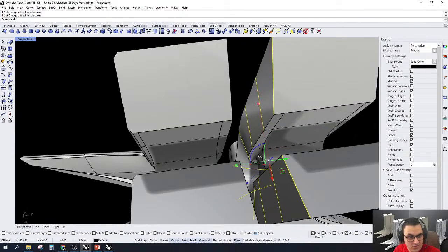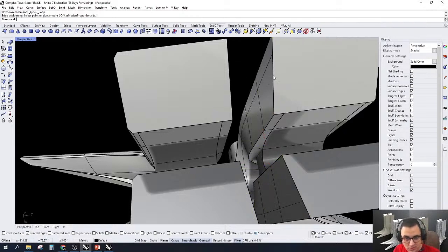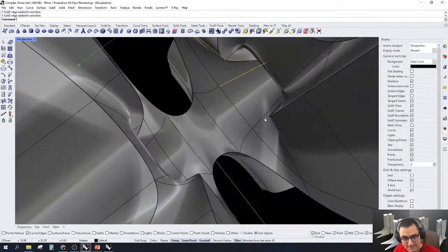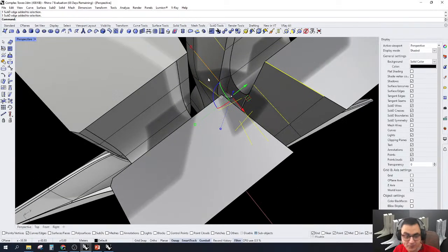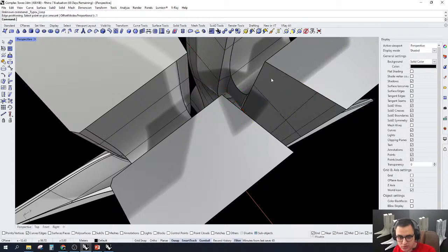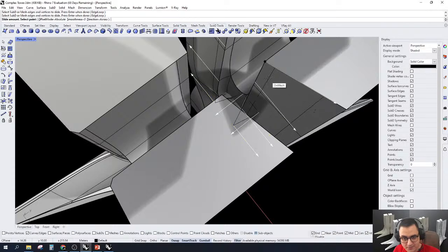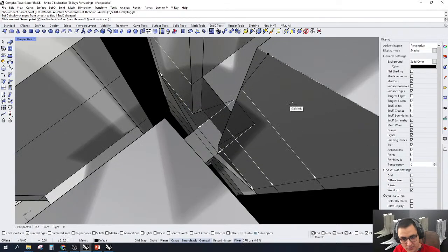And let's go to the subd again, and simply add 0.1, and again let's add insert subd edges and 0.1, and let's slide it. The slide is absolute.